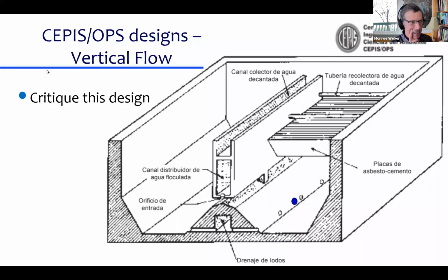What is the difference? Okay, so when the discharge is coming out of the vacuum hose, that's got momentum. It's a jet, and it just keeps on going kind of in a straight line, and it slowly entrains fluid from around it because it's turbulent, and that jet slowly expands, but it travels forward really far as it's slowly dissipating into the environment.